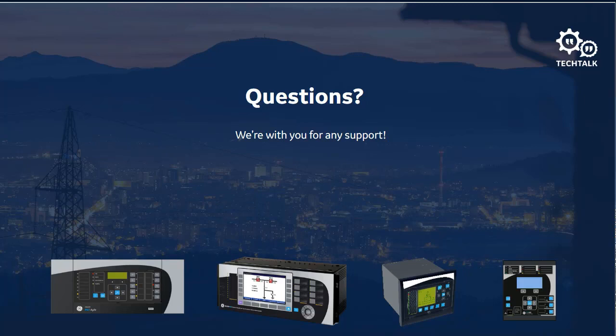Here's another great question. How can ground fault current be larger than 3-phase fault current? This goes back to the example that I gave, where we were given the system impedance and we calculated the system impedance. Assuming an infinite bus, remember, the phase to ground fault current and 3-phase fault current were the same quantity, for a fault on the transformer secondary.